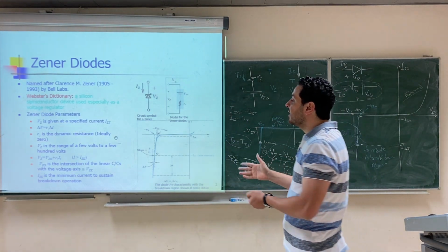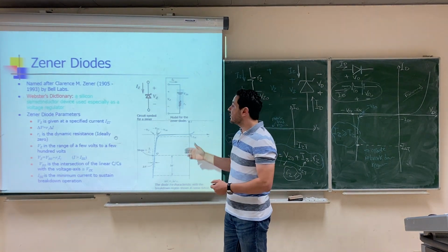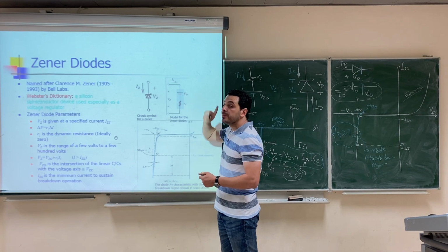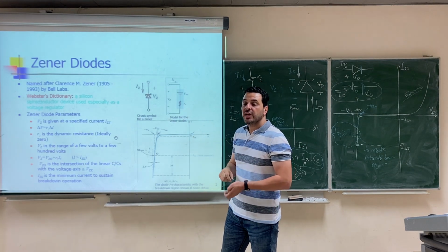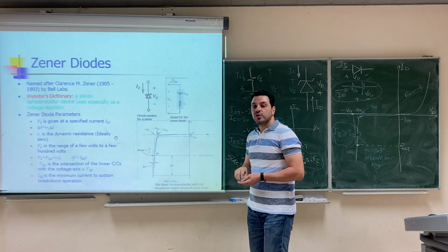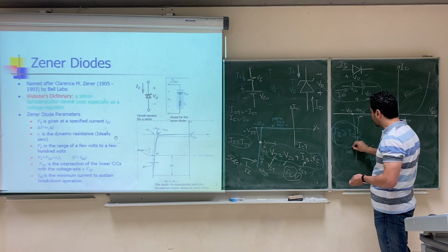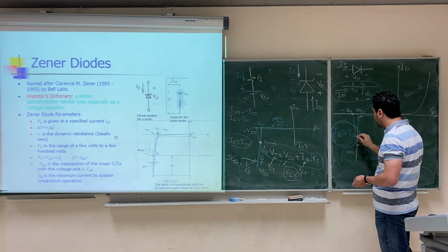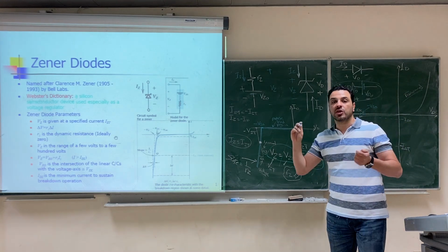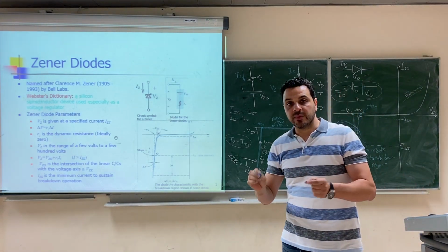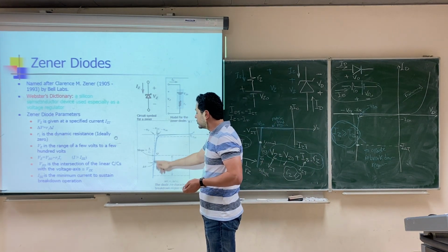So in this video, we defined the Zener diode. We defined the model of the Zener diode in the breakdown region. This model is used only if you assume that it is working in the breakdown region. After you assume and you solve, you have to verify that it is really working in the breakdown region using this condition that I Zener is greater than IZK, where IZK is the minimum current to make the Zener diode work in the breakdown region. If it is not given, then by default you can assume it to be 0. We defined the model RZ, it is 1 over the slope.